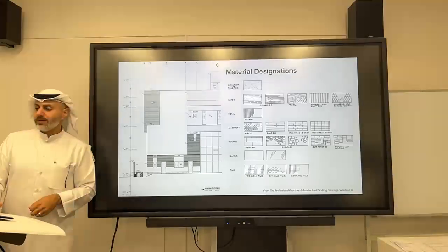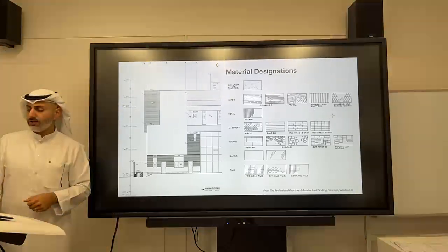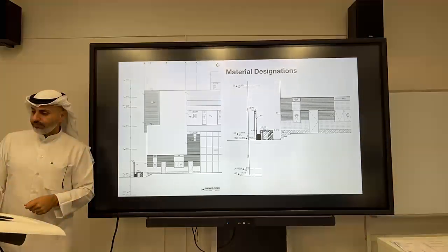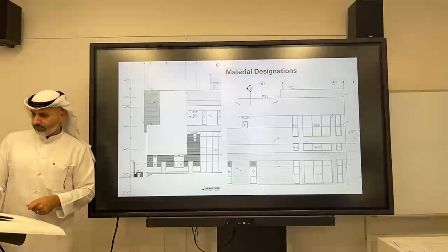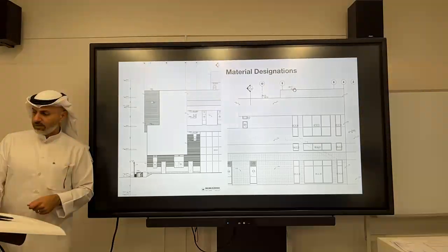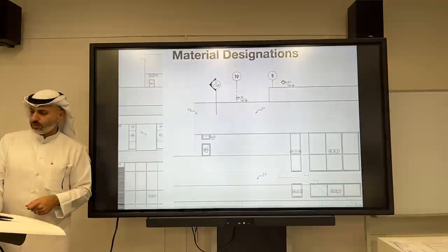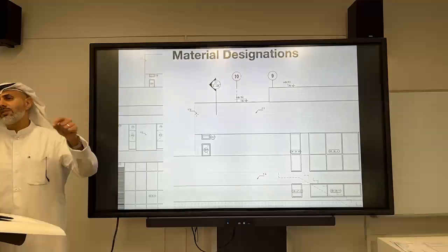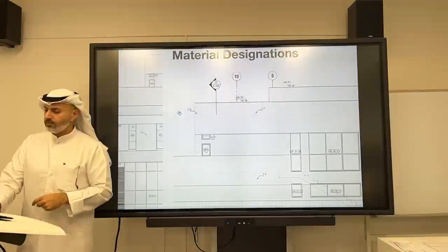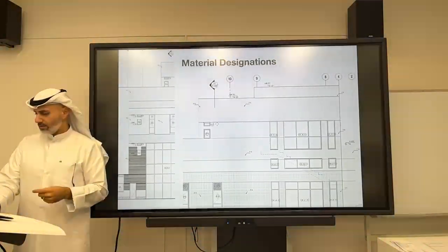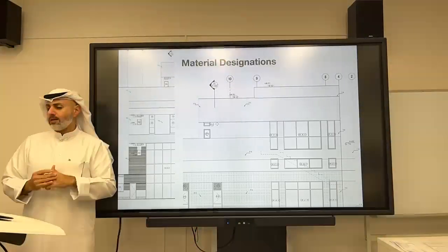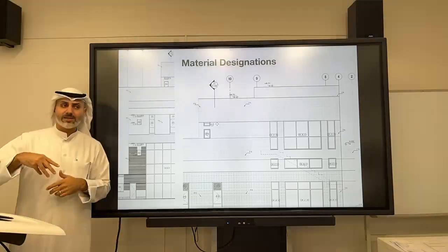How you will show the materials visually. Each material is shown differently. So you'll notice here, this is the TOW, and then it writes what the height is. Each material then has a designation, for stone, like I said, ST01, brick BR01. Sigma, for example, could be something close to the name, or PP for painted plaster. Sigma is a more local designation.